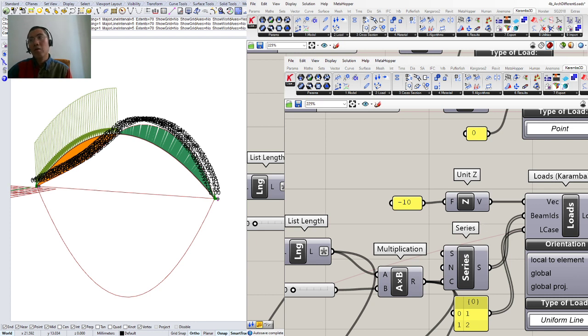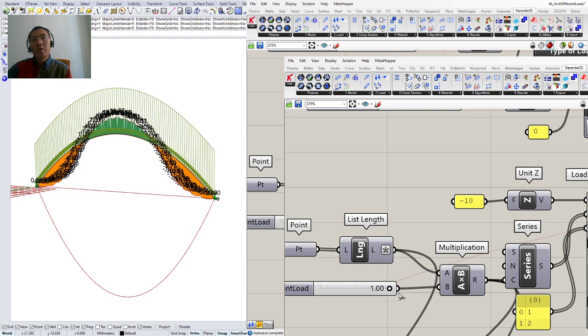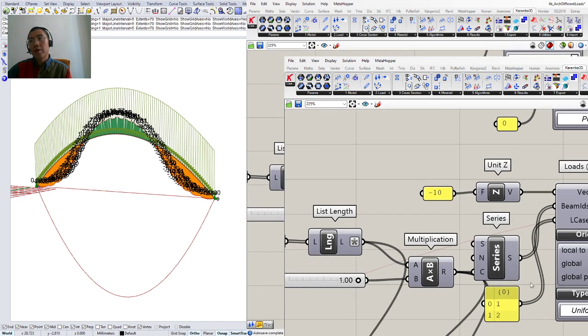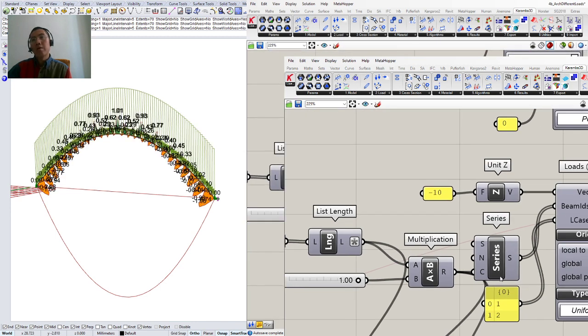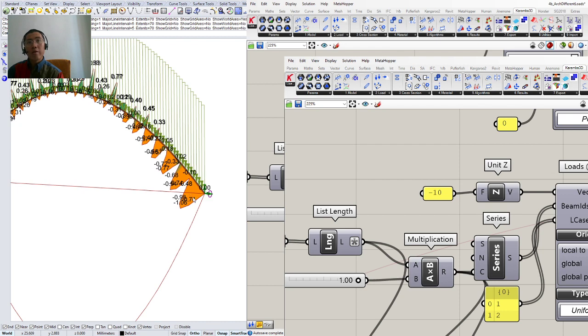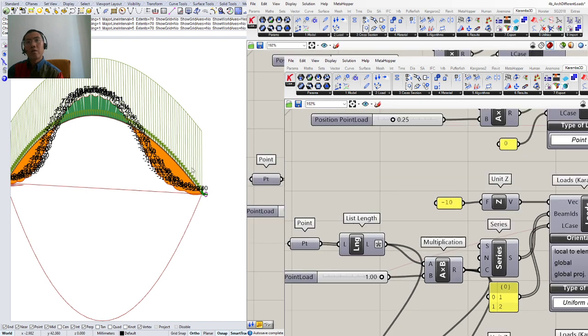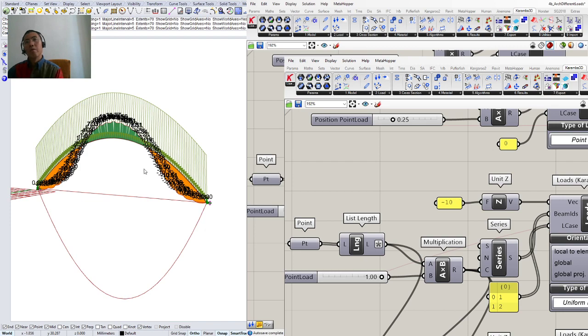If we apply a global load, you'll see that the load distribution is slightly different. And if I apply the load to the entire structure, you'll see that I have much higher bending moments in our structure, as compared to our global projected. So here we have an evenly distributed line load across the entire arch, which is applied as global projected, where we have high moments at certain areas which vary, whereas with the global projected we have a higher threshold for our loads, for our moment forces.